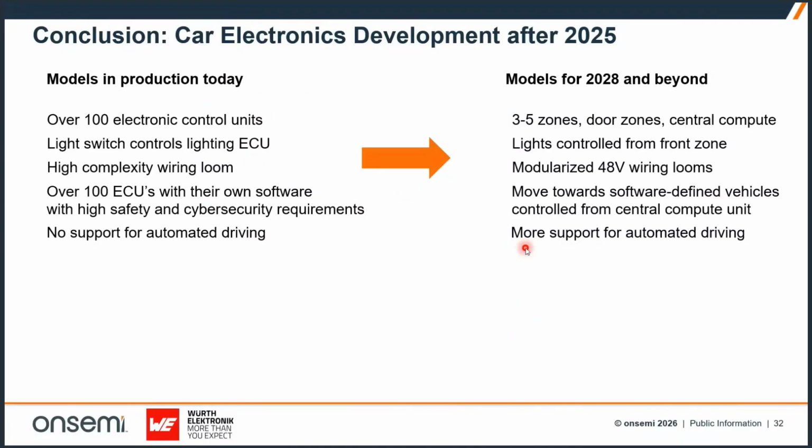That drives the need for Ethernet MAC-PHYs, PHYs, and PMDs, and drives the need for common mode chokes. Lights are now controlled from a front zonal controller or a special lighting module. You don't have the light switch controlling the lighting ECU.